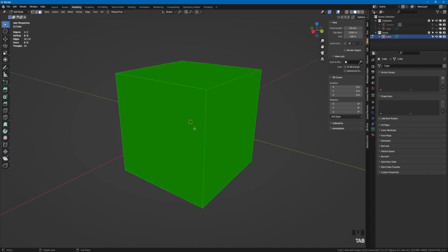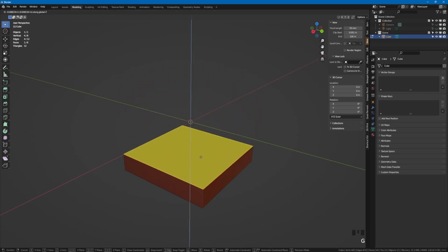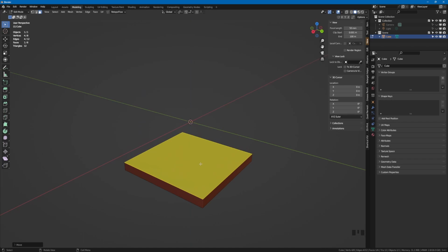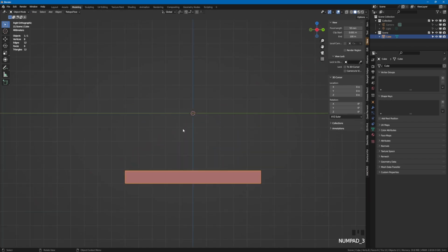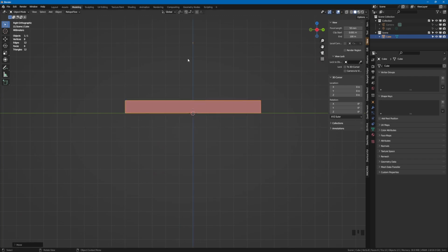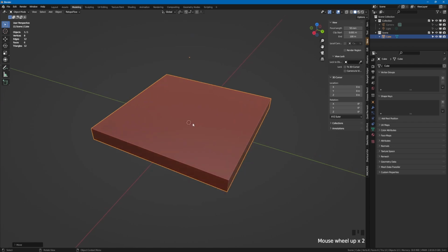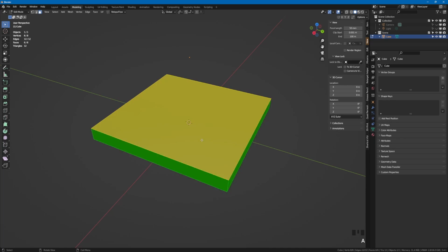Now we reset the height of the cube in edit mode so that we get a floor. Then we set it a little bit higher on the Z-axis. I want to give the floor a UV checker texture. First I set the seams on all edges with Ctrl+E and mark seams, and then perform the UV unwrapping with the U key.